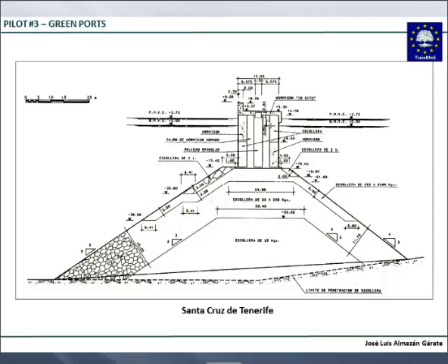In submarines, for example, when the submarine goes deep, it's not affected by the wave. The wave energy is concentrated. So this looks like a Japanese dike, but it is not a Japanese dike. It is a real vertical reflecting dike at an enormous depth. This is 34 meters here, plus the tide. If you look at this without taking account of the depth, it looks like a Japanese dike, but has nothing to do with it. It only looks like it, but it works in a completely different way.